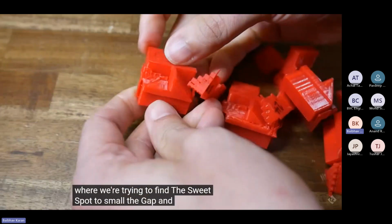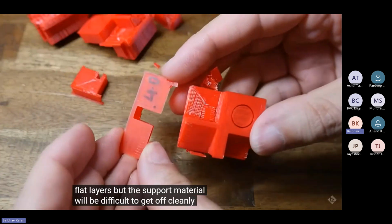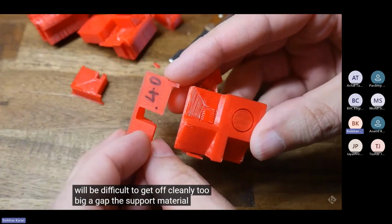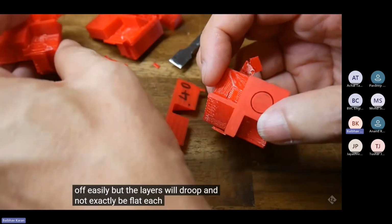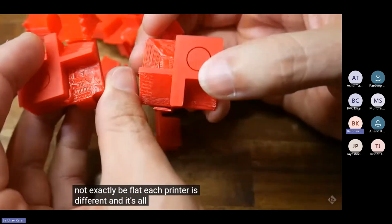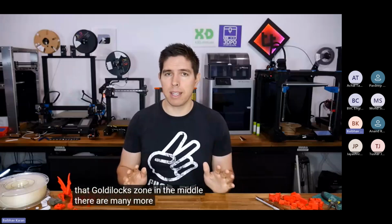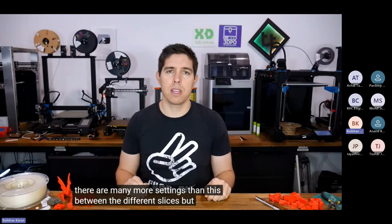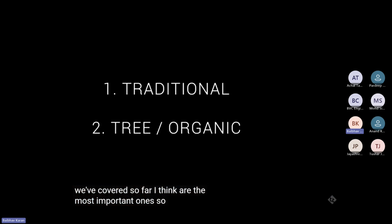Too small a gap and we'll have nice flat layers, but the support material will be difficult to get off cleanly. Too big a gap, the support material will peel off easily, but the layers will droop and not exactly be flat. Each printer is different, and it's all about finding that Goldilocks zone in the middle. There are many more settings than this between the different slicers, but what we've covered so far I think are the most important ones. So far we've looked at traditional support material, but what about tree or organic?